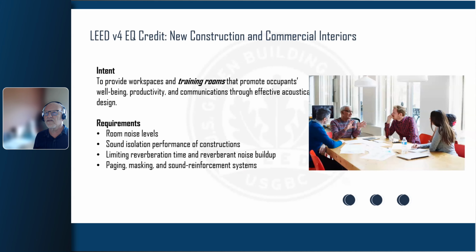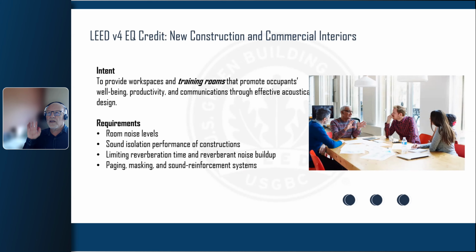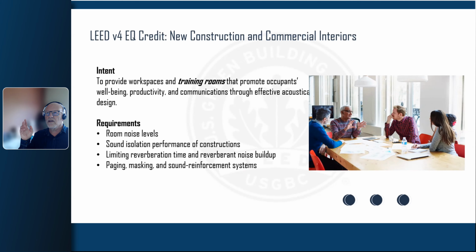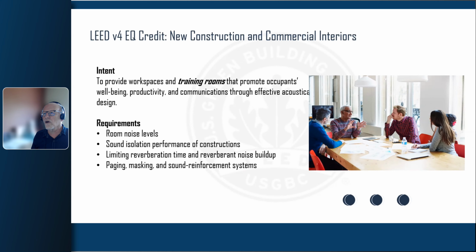You definitely need some kind of seal. It could be a drop seal. The whole issue of seals really ties into the issue of using cam lift hinges, which I didn't really talk about very much today. In that case, you've got a fixed bottom seal and a door that goes up and out of the opening and then closes and sits on that bottom seal. So different seal options are worth noting. But pretty much everyone's gotten away from a raised sill.